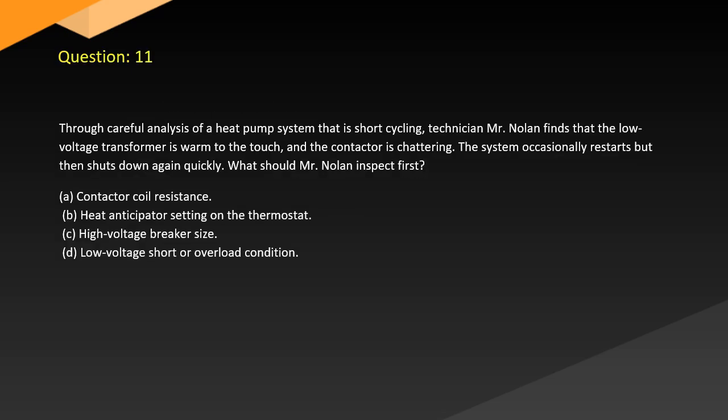Question 11. Through careful analysis of a heat pump system that is short-cycling, technician Mr. Nolan finds that the low-voltage transformer is warm to the touch and the contactor is chattering. The system occasionally restarts but then shuts down again quickly. What should Mr. Nolan inspect first? A. Contactor coil resistance. B. Heat anticipator setting on the thermostat. C. High voltage breaker size. D. Low voltage short or overload condition.